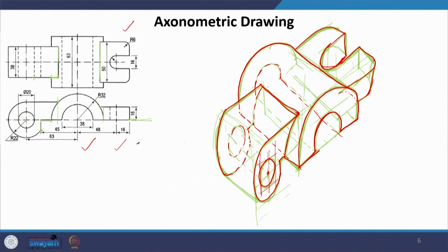So, for example, in this case, we derived where this point is going to be, and this was the other point, and we simply understood that this is going to be the curve which is parallel to the original curve, the actual curve of the main object. And that is how you could derive the axonometric view simply from this given orthographic projection. We did not even have to measure. The simple thing you will do, when you draw it at home, is to just rotate it and start giving it certain heights, whatever the drawing is.